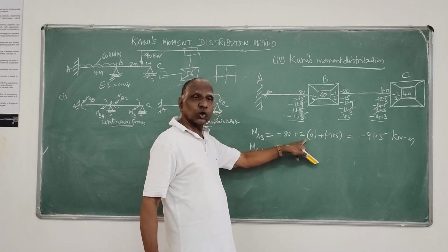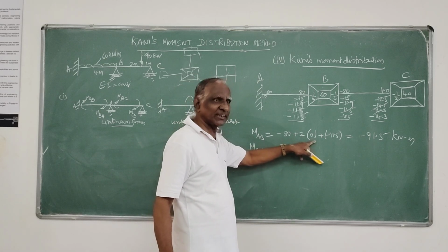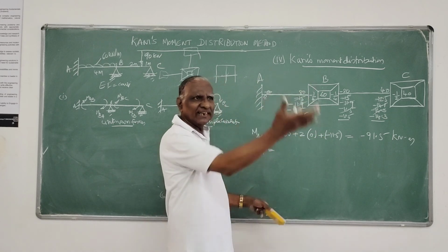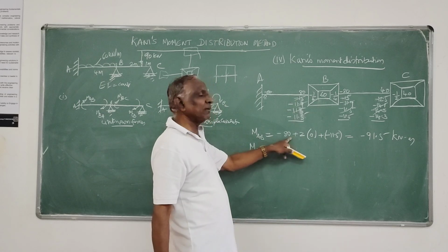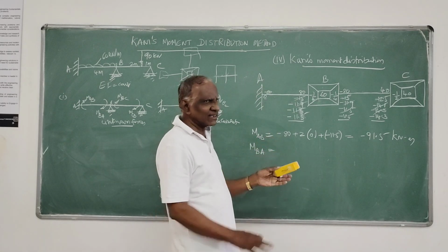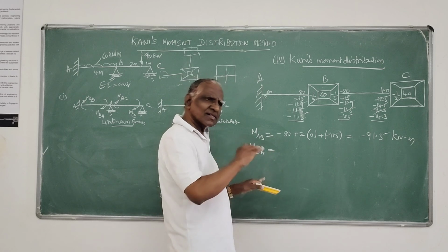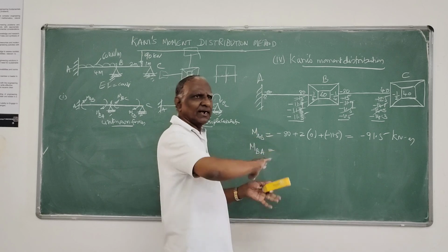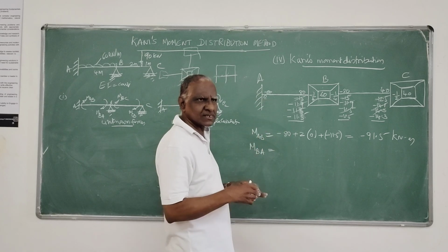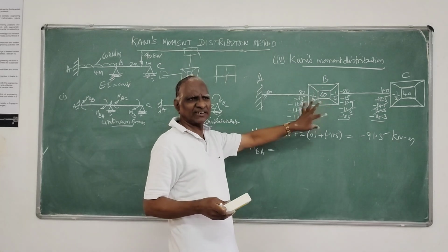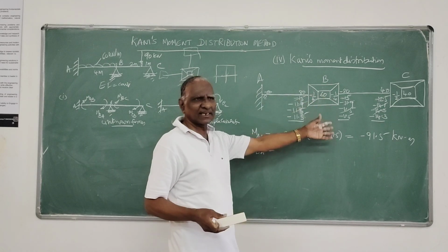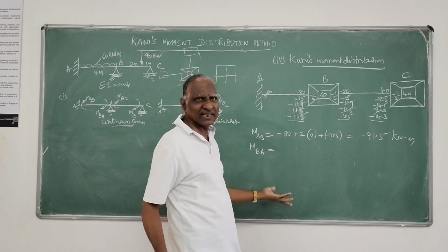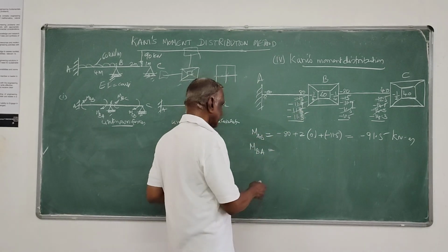This is exactly the slope deflection equation: 2 theta A near end plus theta B rotation at further end, then 3 delta by L, and MAB bar, that is fixed end. There is nothing much in this, all the same type of equations we are using. That's force, displacement and their relationship. That's why it's called displacement method. Or in a different fashion we work it out in diagram fashion, because no equation is involved, no solution. This becomes easier. That's all, nothing other than that.